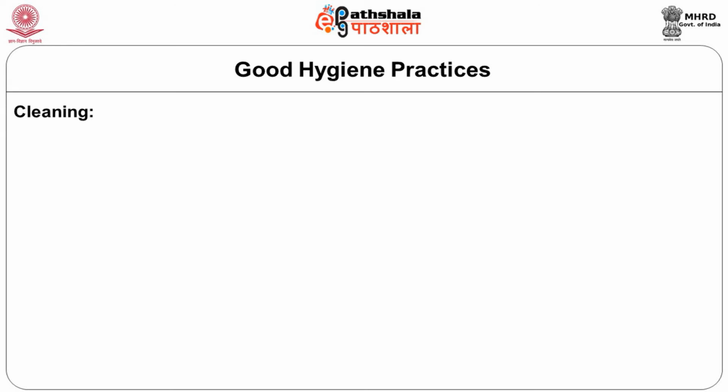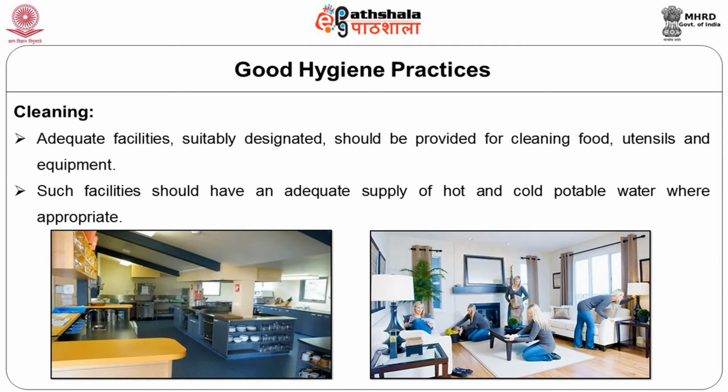Cleaning is the most neglected area in the food processing area. People will not bother much once the process is over, and the cleaning is not properly done. But adequate facilities and suitably designed cleaning procedures should be in place for cleaning food utensils and equipment, and such facilities should have an adequate supply of hot and cold potable water wherever appropriate.